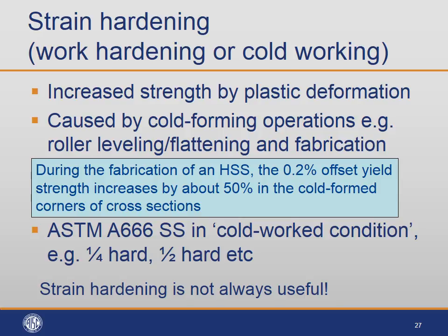You'll appreciate that strain hardening is not always useful. When you're fabricating stainless steel, it means you need more powerful equipment, stronger tools, greater forces. And strain hardening can also reduce ductility. However, the ductility of stainless steel is so high anyway, that's not usually a problem.